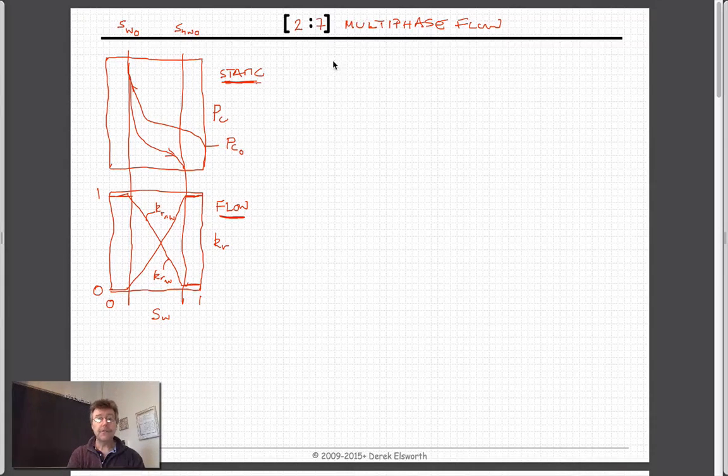Those are the key concepts. We talked last time about L-NAPLs and D-NAPLs, so let's rationalize exactly what's going on with L-NAPLs. What we'd like to do after today, section 2.7, is actually multi-phase flow, talking about the unsaturated zone, where the two phases present are water, in the pores, and gas, air, basically nitrogen.